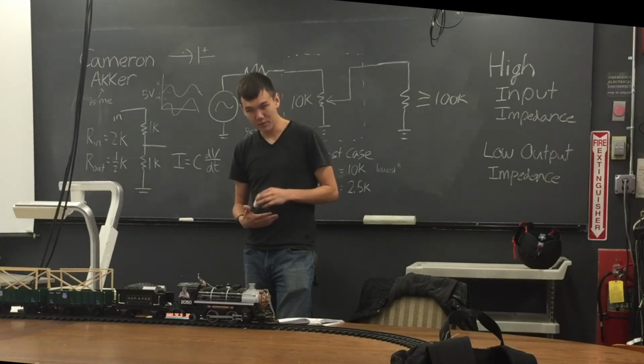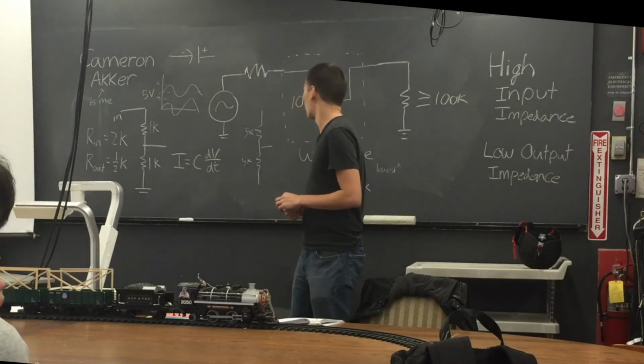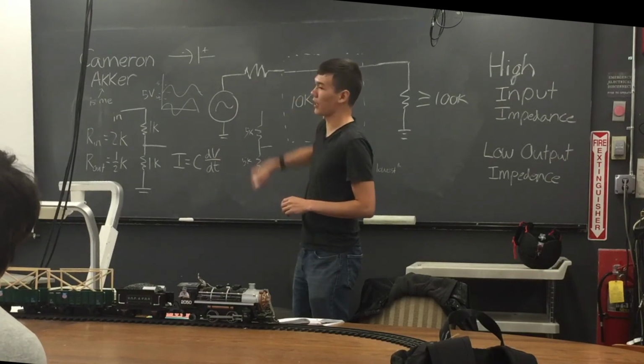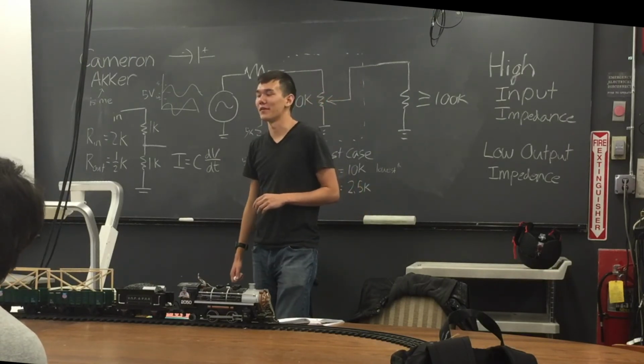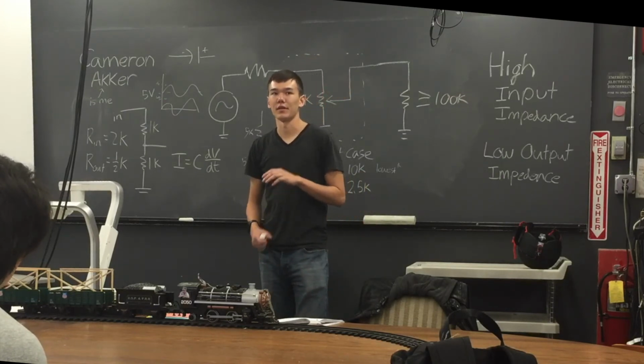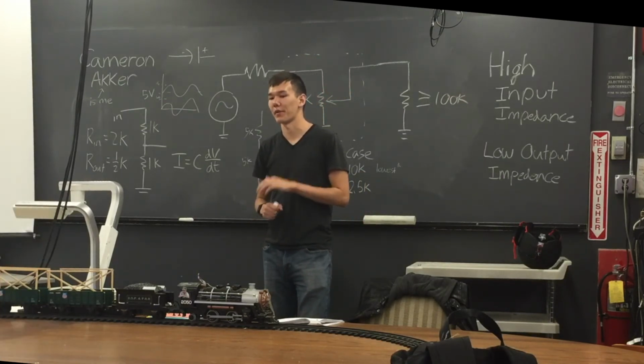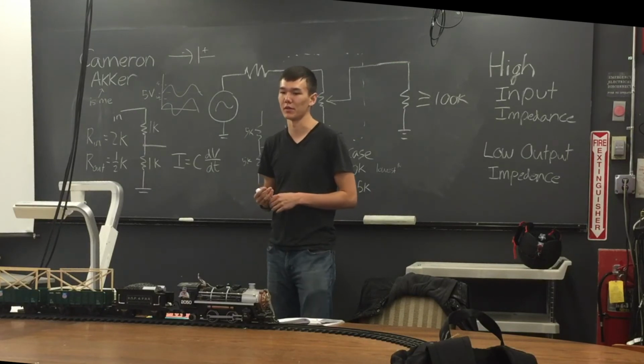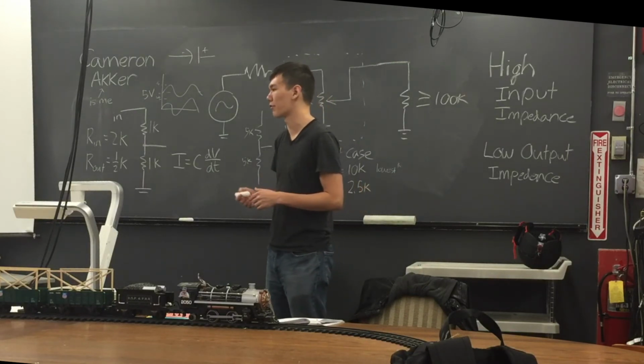Let's see. So what's a good value for the decoupling cap? Usually in the labs, when they tell you to use one, they'll give you a value. I'd say 0.1 microfarad or something. It's rough. It doesn't have to be anything particular, or even 1 microfarad.